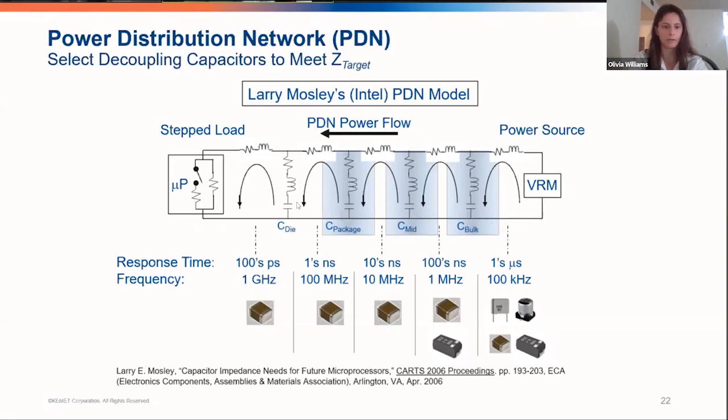And finally, all the way down to the internal die capacitors. And the PDN impedance seen by the load is the parameter that determines the peak voltage deviation during the fast transients. So the system requires this low impedance network over all of the frequencies to ensure that the deviation remains within an allowable voltage range or threshold.